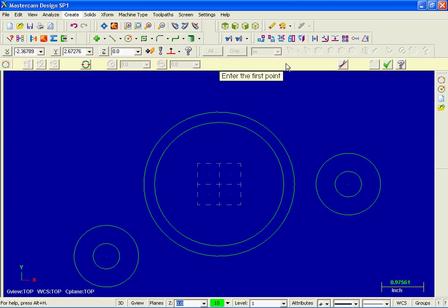Now over on the right hand side of this ribbon bar, I'm going to click on this button for tangent, because these arcs, these circles that we're trying to create, are tangent to two entities. Now slide over to the left and in the white space for radius I'm going to input 5.0.